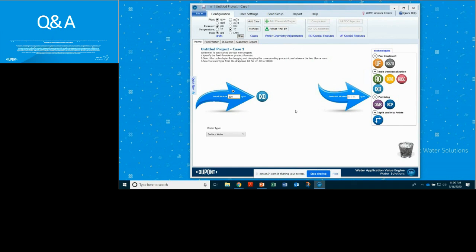But things to be aware of: it's not the same as running a sodium form strong acid cation resin. The process of running a sodium form WAC includes an acid regeneration as well as typically caustic for conversion to the sodium form, as compared to strong cation, which is converted using sodium chloride. So it's generally not the same cases that you're considering one versus the other, unless it's borderline, or maybe there are additional factors, but at a high level, those are some things to think about.